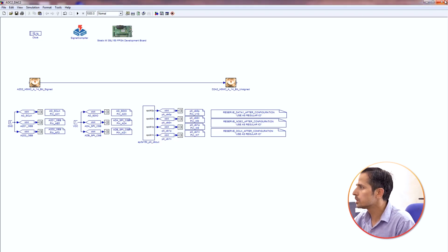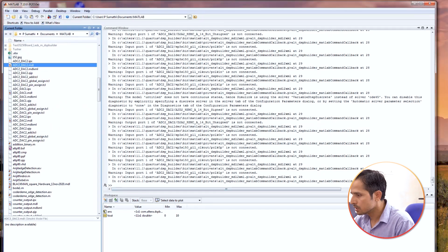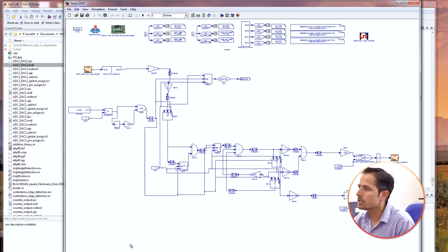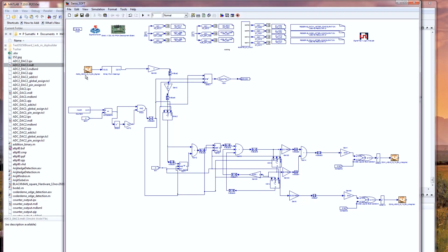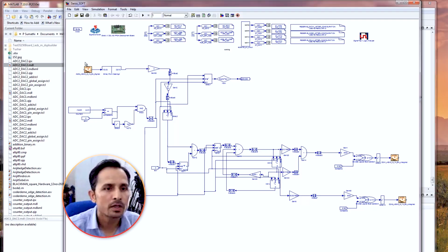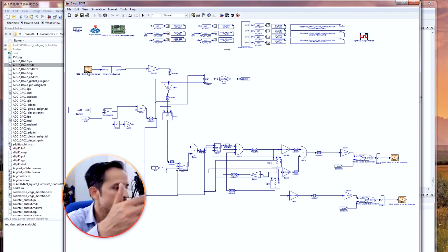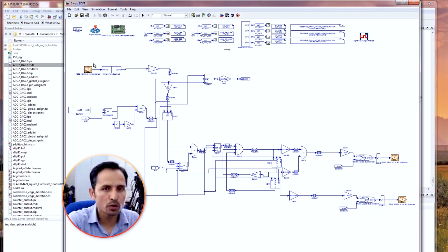So I will be closing this one. Now this is the Sliding Discrete Fourier Transform program. Again we are connecting this input signal to the second ADC, and then we are passing it through the binary point casting. What happens is that when we give the signal to the ADC, it gives signed values, so it will be on the positive side and also on the negative side. So we have to truncate this signal so that it can be passed through to the program.